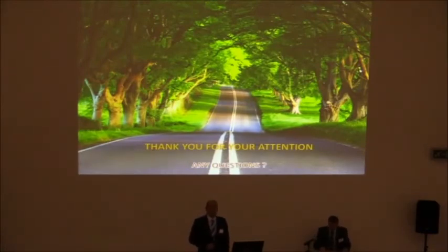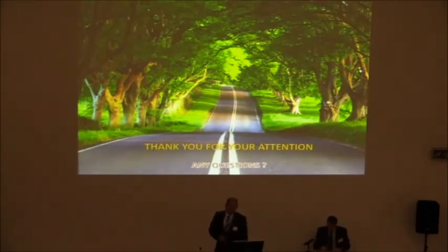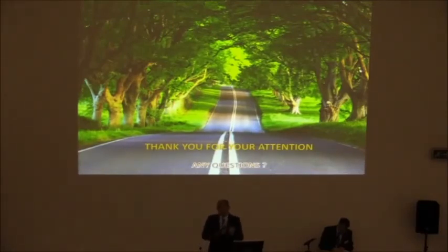Very good presentation. My question is, why is this material's strength increasing with its age? Because normal hot mix, its strength is fixed. Yeah, because our waste material has a cementitious activity. So it's like cement. We need to replace the cement used previously to enhance the cold mix. So we replace the OBC and we put waste fly ash, and it has cementitious activity. So there is a hydration process, and there is water, and that enhances the stiffness.